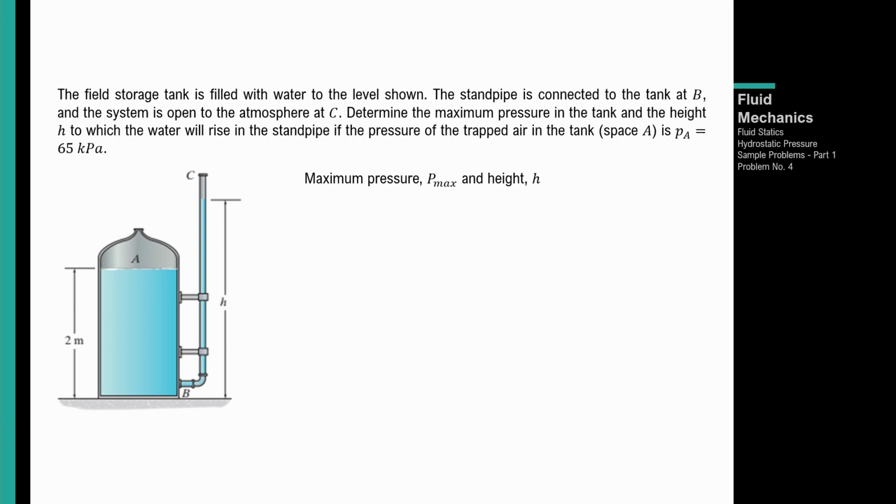If you noticed in the figure earlier, what is inside the tank or bin is suction, so negative pressure. So on the right side, the level of the ethyl alcohol is lower. Here, since the pressure inside the tank is high, it is positive pressure. So the right side, which is open to the atmosphere, has a higher fluid level. Here is the water. So we need the maximum pressure.